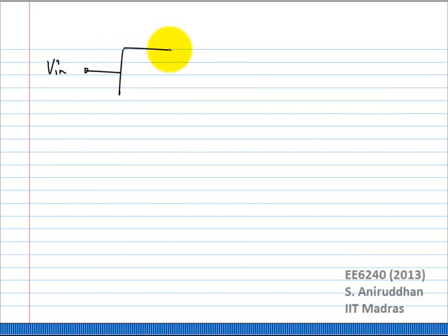Now remember, what I really want for this is I not only want the 90 degree phase shifted version of the signal, but I want the original signal itself also. Because I'm going to use this 90 degree phase shift to actually differentiate between the image and the RF signal. So to do this, I actually need to preserve both the original signal as well as the 90 degree phase shifted signal.